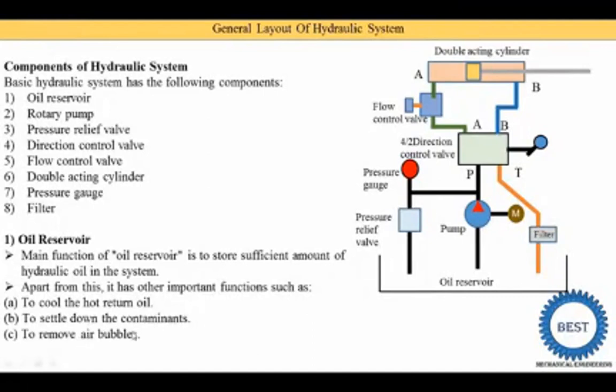To remove the air bubbles. Why is an air bubble created in oil? When the temperature of the oil is increased, by default there is a possibility that bubbles are created inside the oil. So we need to remove these air bubbles from the system.